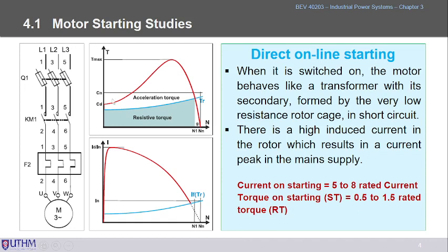So you can see the performance of the DOL starting in the illustration here. This is the starting current, and this IN is the nominal current. So you can see the huge increase during the starting. So for the DOL, it is 5 to 8 times.